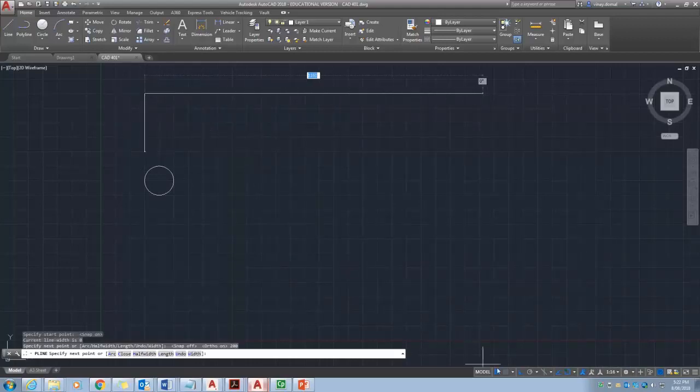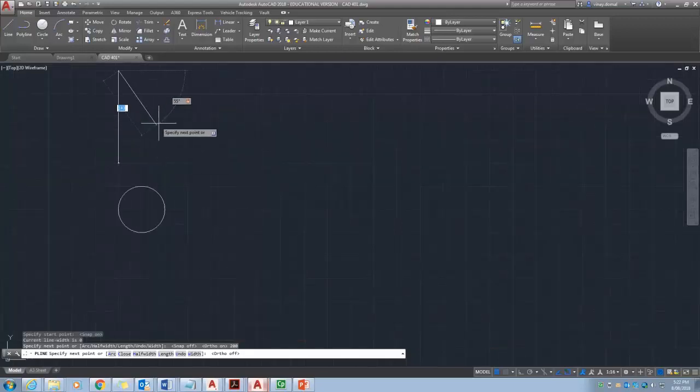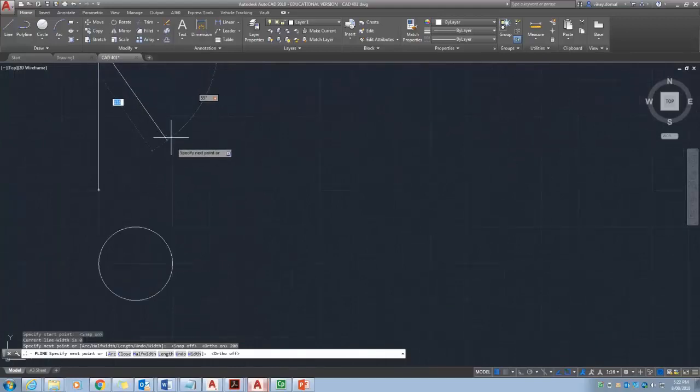Now deactivate your ortho because you want to subtend some angle. Press the tab key to make that angle 55. Don't press enter, tab again, because you don't know the approximate length. All we know is that it stops at the alignment of this end of the circle here. So you can infer that end by clicking into the quadrant and coming back to find the inference line there.